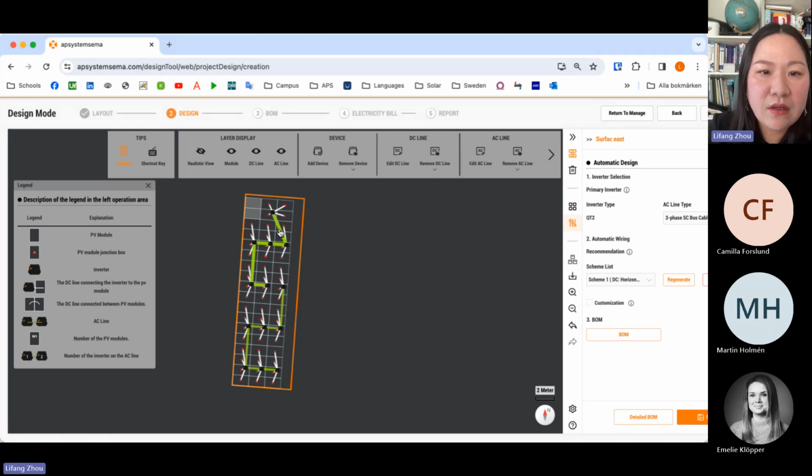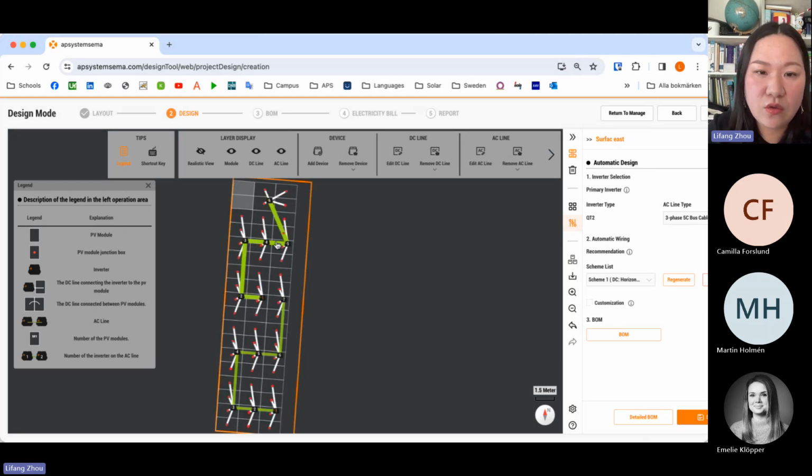If we zoom in a little bit, you can tell the microinverters are connected by the AC cable with the nearby AC cables, and also the DC cables connect the solar panels. The maximum for one string of these microinverters is 7 units of QT2 you can connect. After that, you have to start another AC string, with another maximum of 7 units on the roof.